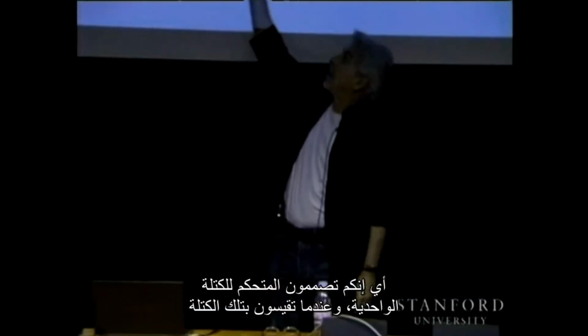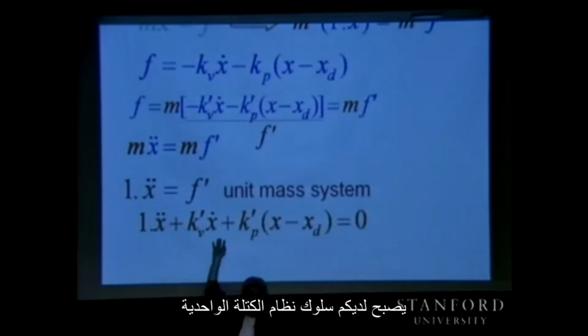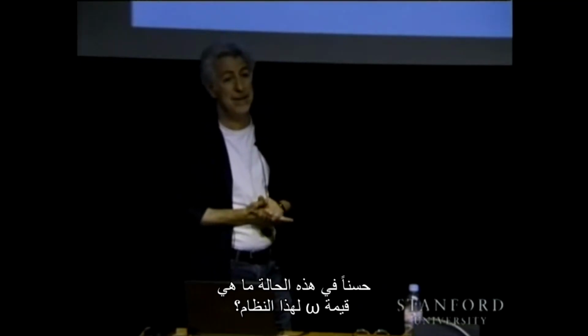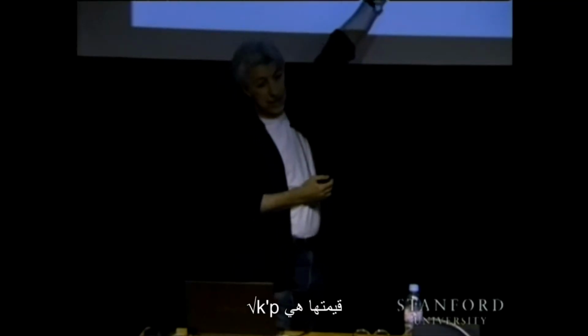So you design your controller for the unit mass, and basically if you scale with that mass, then you have the behavior of the unit mass. Okay, so in this case, what is omega for this system? It is simply the square root of Kp prime.